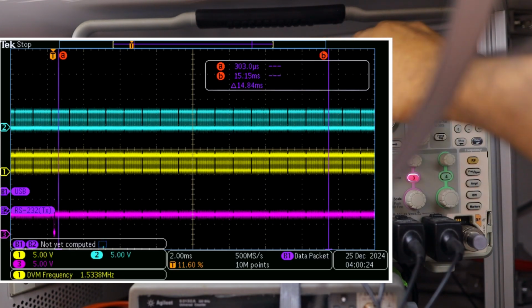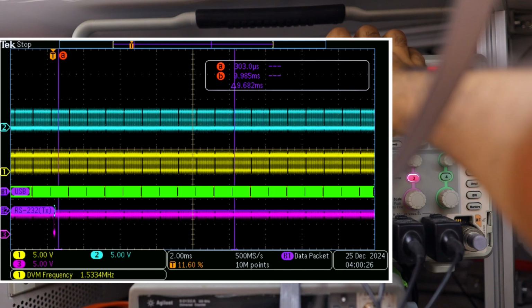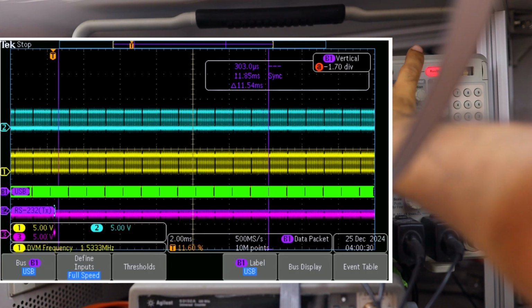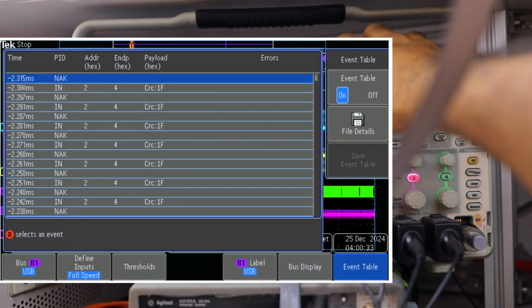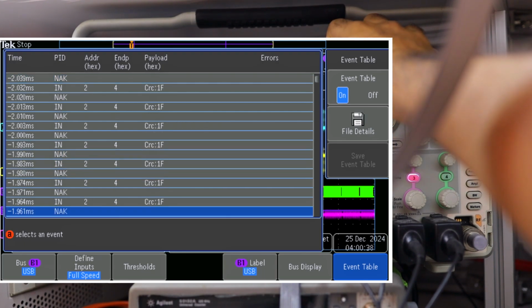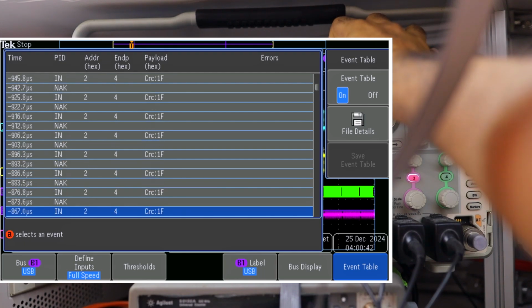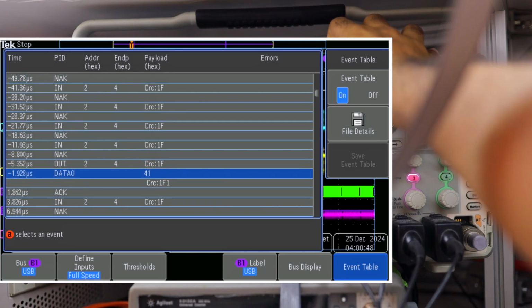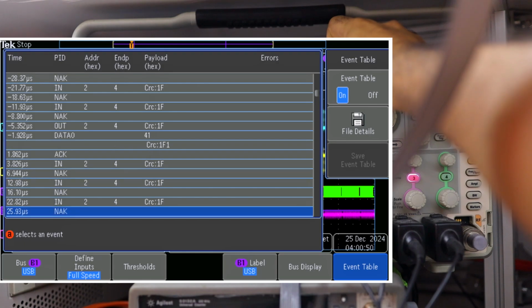That's my UART. And here, somewhere in this whole area, there must be a USB packet going back. I'll try to manually find out. Okay, so let's see if, first of all, we detect data coming in. The time must be almost 0. 900 microseconds. That is my data A, ASCII A, 41 hex.